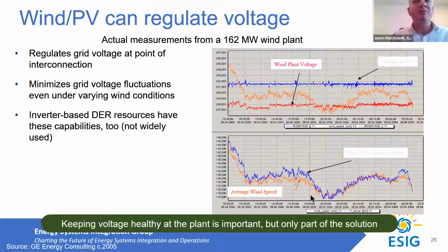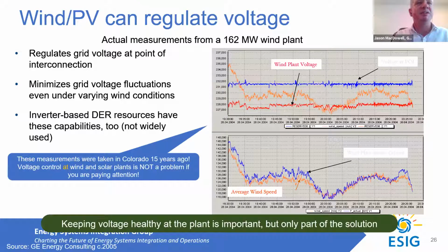So when the power fluctuates, you tend to have fluctuations of voltage as well, because you're trying to maintain balance, right? Of losses of real power capability into the grid, but also that reactive power capability is tied to the real power balancing and the real power fluctuation. But fundamentally, it's not a concern. We have closed loop plant level voltage control on the system today, and it works just fine on all inverter-based resources.